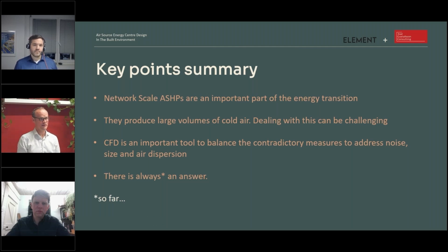So I think yes, you can use more electricity for the same outcome, and the intermittency that thermal storage in particular assists with is an interesting factor. And I think we are seeing that in most energy centres. The energy centres that I showed earlier in the scheme will also have big electric boilers to take out, say, negatively priced electricity or ultra low priced electricity. But the heat pumps are going to reduce demand considerably for the remainder of the time when electricity has a higher cost.